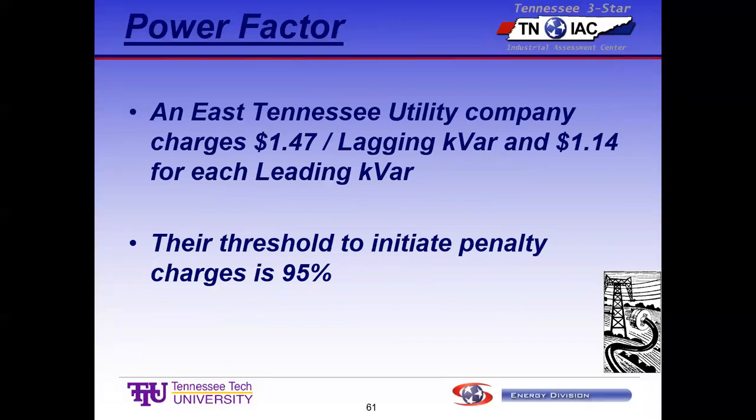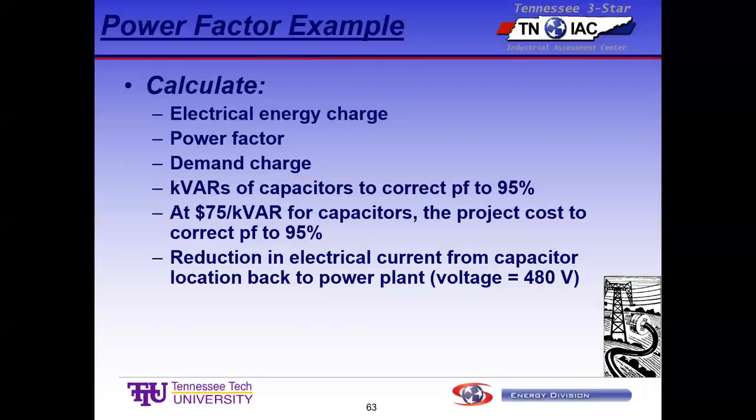This is fairly typical. On the rate structure you have, they measure the kVAR. There is an allowable kVAR. Anything over that, you have to pay. You pay based on the kVAR instead of going through this kW thing. I think it's like $1.46 for a lagging kVAR, and it's usually something like between $1.10 and $1.20 for a leading kVAR. So anyway, I think that's enough of this.